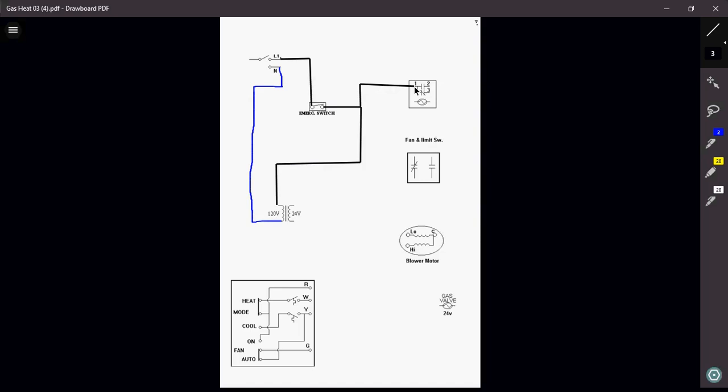I'm not going to be able to achieve the temperatures that I want coming out of my supply ducts. Usually we want somewhere maybe like 120, maybe 130 degree air coming out of there. Again, it depends on manufacturer specifications. So I want my fan to be in low speed.